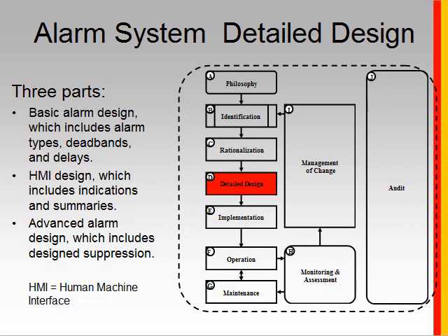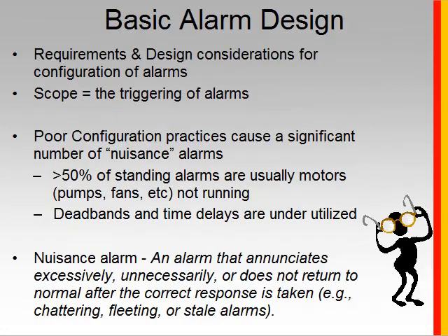It consists of 3 activities: the basic alarm design, which deals with the triggering of the alarms, the HMI design, which deals with the presentation of the alarm to the operator, and advanced alarm design, which deals with potential suppression of the alarms during critical operating scenarios. So let's take a look at these different activities.